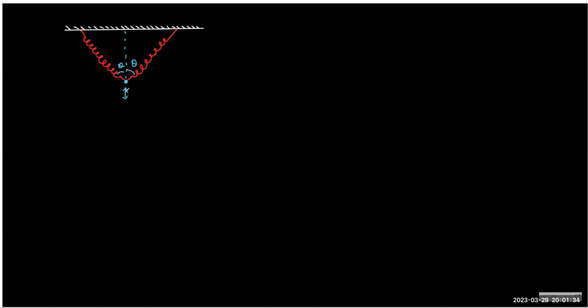You have to displace and find the net force, and then you can replace that net force by K equivalent into Y. So if I displace by Y, my net force should be... If this is L naught, this is L naught, this is K, this is K, and you stretch by Y, then it should exert a force of K effective into Y, and the same force this particle must experience when we stretch down.